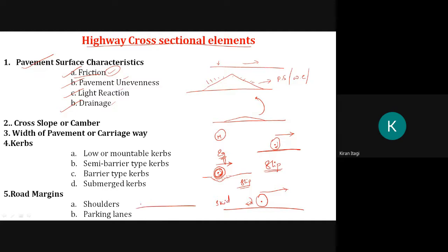For example, in your childhood days, you took a bicycle, came at a certain high speed, and applied the brake, the back brake. Applying the brake at the back wheel arrests the rotation, so the wheel will not rotate, but your cycle will move forward. So this is the difference between skid and slip, just to give information about friction.